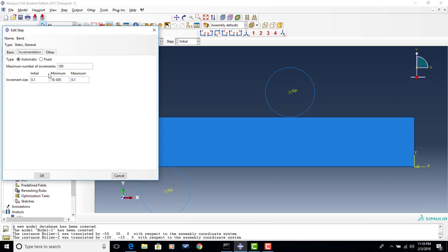So assuming that we don't run into any issues at all, it should complete this model in 10 even increments, and I'll be able to create a small video or animate this or just step through the contour in smaller bits, so that way we can see how the stress or how the deflection or whatever it is that we're interested in looking at developed throughout the problem.